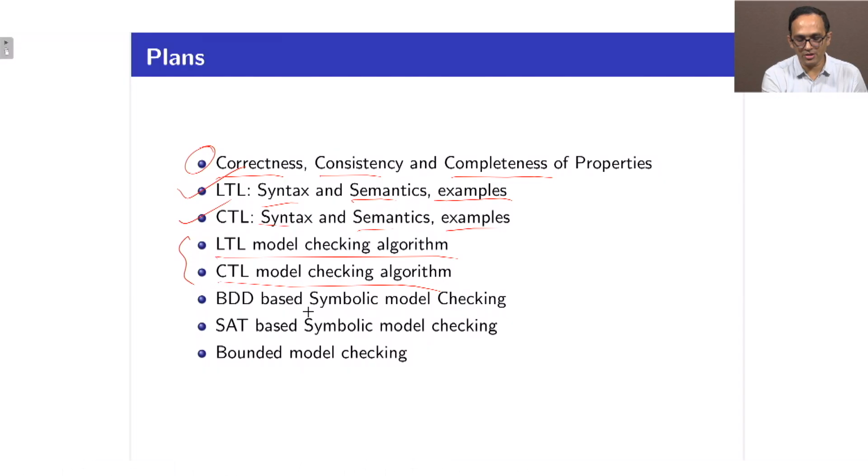So, in many cases this model checker is not scalable if you try to explicitly model your state transition system, where the state explosion problem happens. So, a lot of tricks have been developed, which is called symbolic model checking, where we do not want to extract that exact explicit model, because that will create a state explosion problem, but I can model my state transition system as a BDD.